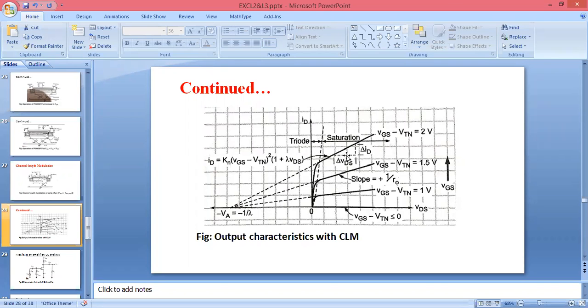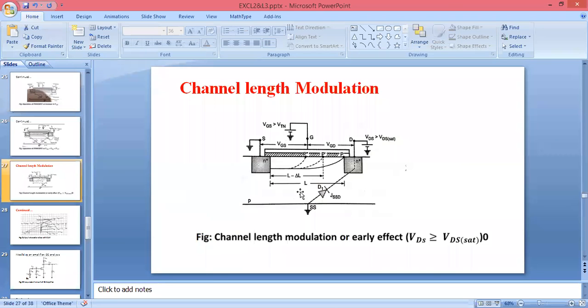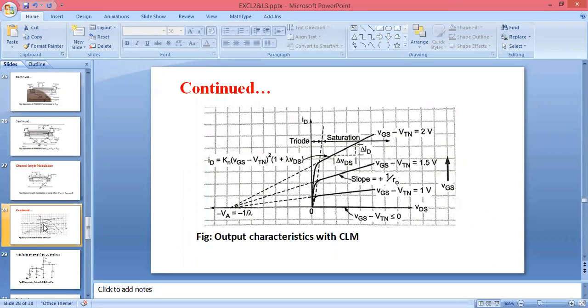Depleted जो area है on channel will increase here, जो depletion area है, and due to which we will get an increase in electric field. That's why we will get an increasing value of the ID current. ये जो ID current है उसका value हमें क्या होगा, यहाँ पे increase हो जाएगा when we are giving VDS greater than VDS saturation. It means as VDS is increased beyond VDS saturation, ID will increase.